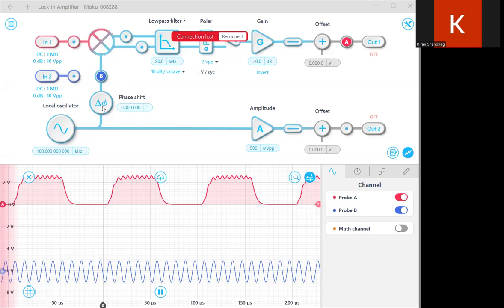And you can see it works by using this local oscillator; we will multiply the signal, so it all works the same. Whether ASK, FSK or PSK, it has a multiplier, and cos A multiplied by cos B gives half cos(A plus B) plus cos(A minus B).